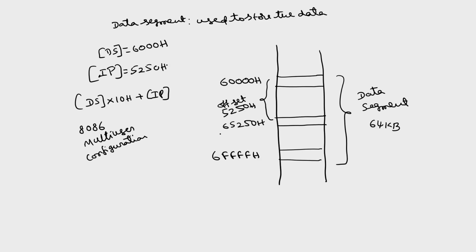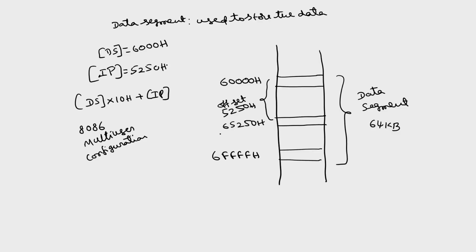8085 is only single user, only one user can program that particular 8085, whereas in 8086 we can have multiple users, more than one user can access the same 8086. So this memory segmentation enables the 8086 to be accessed by multiple users. That is another advantage of the memory segmentation. One more advantage is that using the 16-bit address of the segments, we can access the 20-bit physical address. So these are some special features of this 8086 compared with the 8085, where segmentation is not possible.